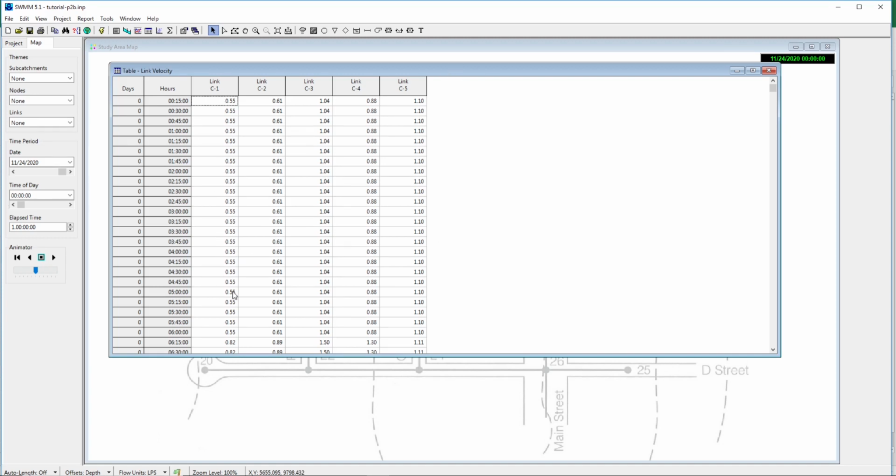For pipe number 1, the velocity is less than 0.6 for some time, but during 24 hours, as we can see, the velocity goes beyond 0.6 as well, which means it is not going to be a problem. So all the velocities, as we can see here, they are within the range.